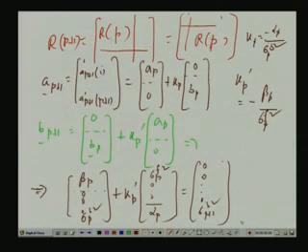In fact, there is no time to go into all those details, but K_p and K_p prime can be shown to be the same in this equation. In fact, one is the conjugate of the other, to be frank. K_p prime is the conjugate of K_p and vice versa. Sigma_p b square and sigma_p f square are the same, that comes from stationarity. These results I am not showing here. Okay. So, from the past solution you can find out the future solution. The only thing is how to start the recursion.